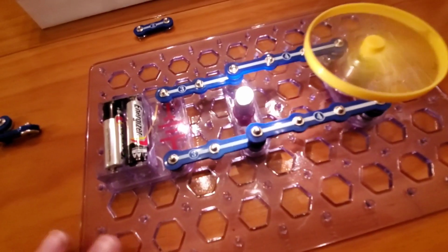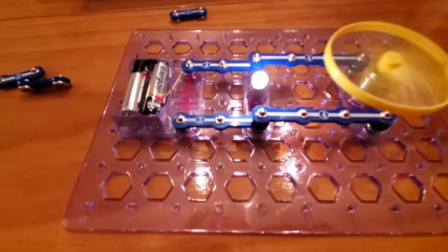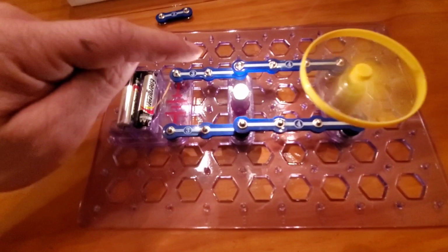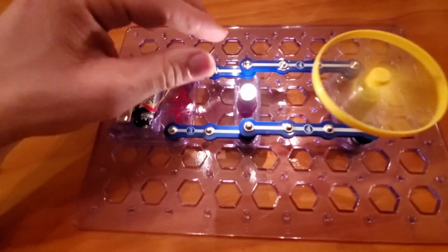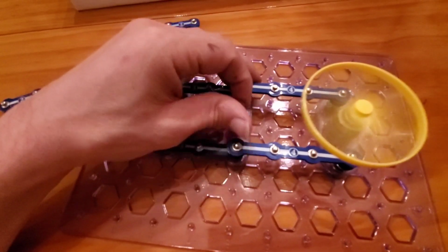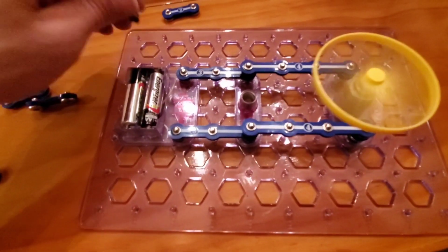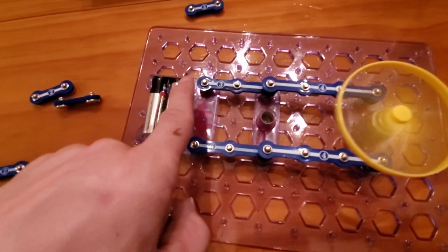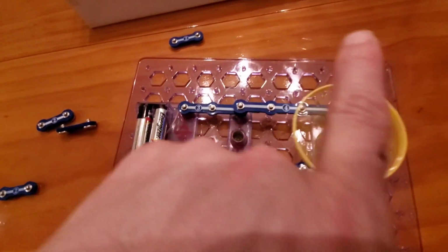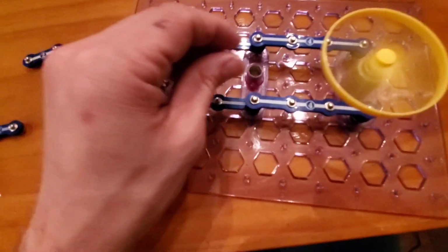So let's check to see if this is a true parallel circuit. If it is, I should be able to remove one of these things, like let's say the light bulb, and the fan should stay on. Remember before, I removed the bulb and the fan turned off. So let's find out. Yep, still works. So, guys, this works because there are multiple pathways. So electricity can flow from here, through the light bulb and back, from the battery, through the fan and back. So if I remove this one component, the fan can still stay on.